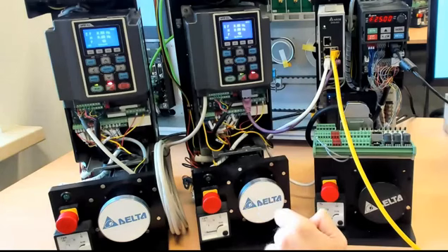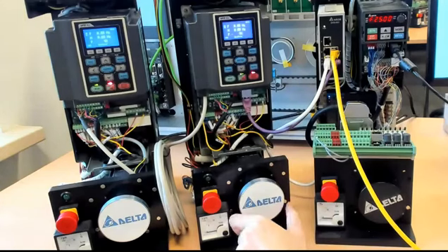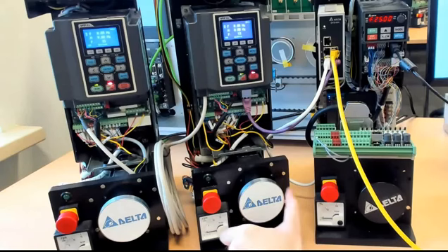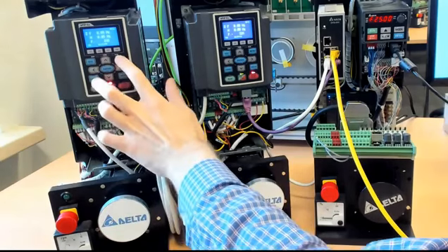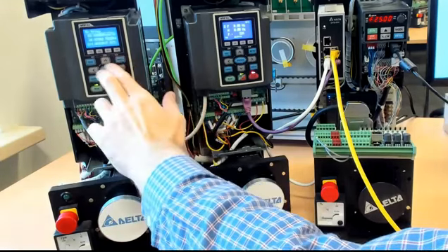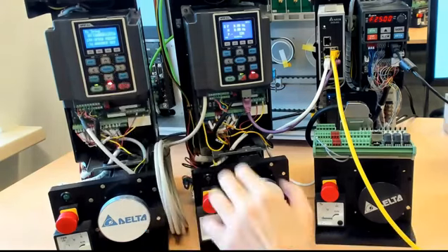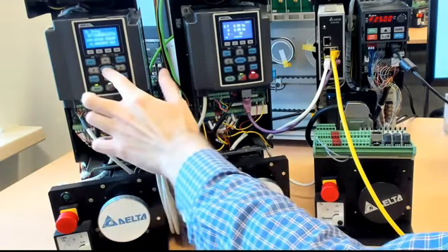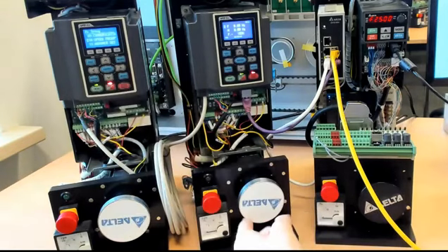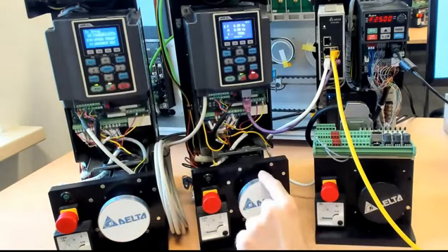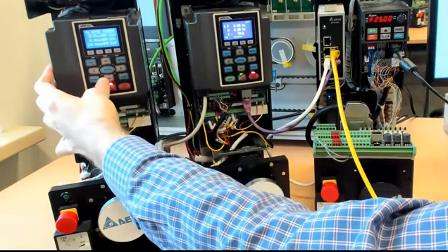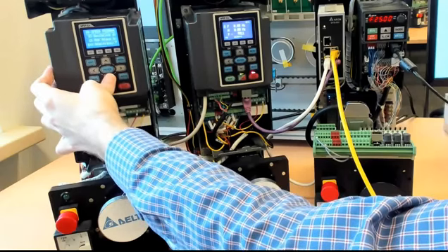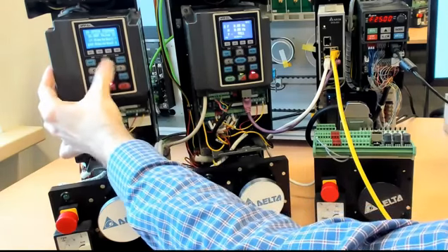This is basically it. After you configure the drive in field-oriented control mode, you just need to set these 4 parameters, and you're ready to start. You can also set different ratios between the master and follower. Right now it's a 1-to-1 ratio, but you have some electronic gearbox parameters, so electrical gear.